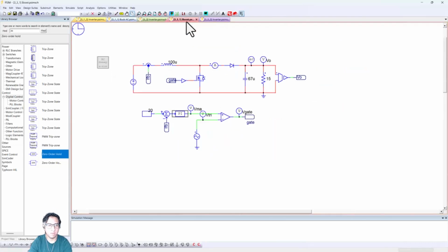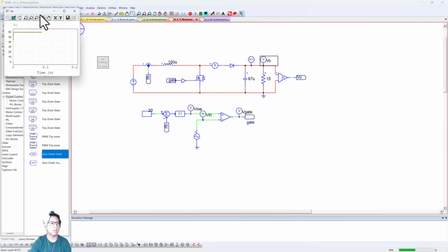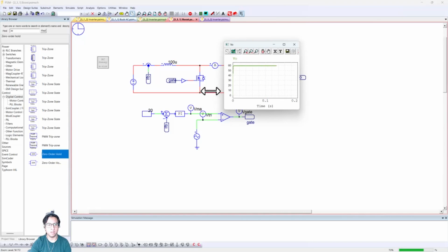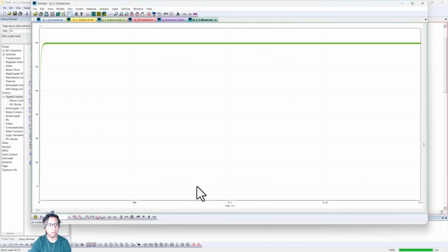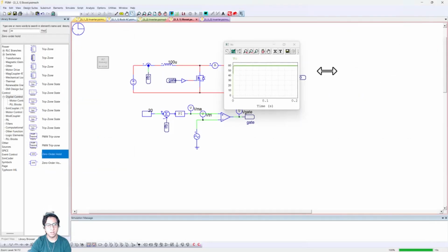So these two examples will deal with how to debug a converter, or some examples of controllers that fail. Specifically, this one is a controller that's not doing its work, but it apparently is, right? So let's simulate it. And if we start looking at the output here, we'll see that it is reaching steady state. So this is current controlled. So we're just looking at the voltage, for instance. We see that it is actually doing its work.